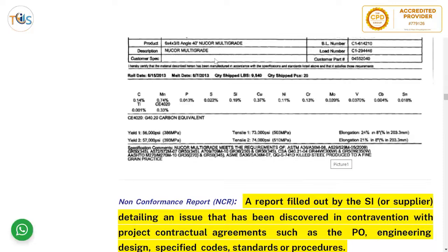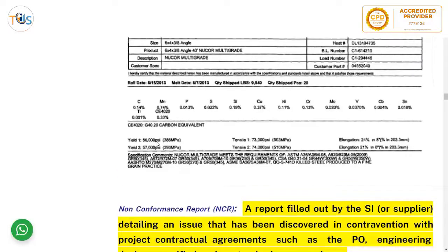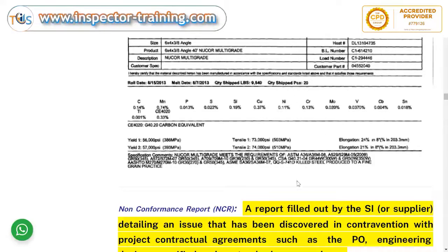So it's practically telling the chemical composition, the traceability, which is here on the top, the strength, the tensile test, and it tells you also how it was made. And to see that this was actually according to, say, ASTM A36, you have to go to ASTM and see that this mechanical test and chemical composition falls within the range of what ASTM A36 tells us.